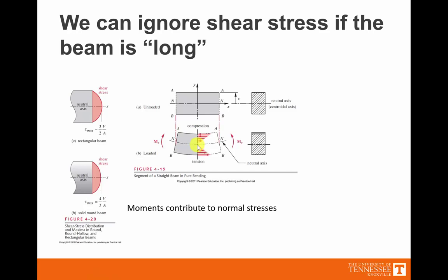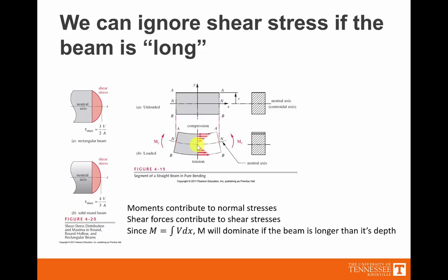Also, if you consider that moments contribute to normal stresses, shear forces contribute to shear stresses, and the moment is the integration of the shear. So the longer the beam is relative to its depth, the more M is going to dominate, because we're integrating along dx as we move along. So what that means for us practically is if the beam is 10 times longer than it is thick, we don't really even need to consider the effect of shear.